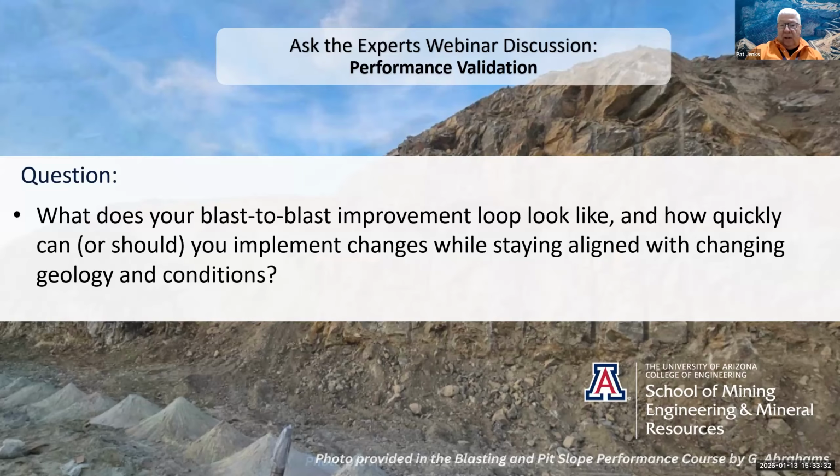Oftentimes that manifests as an increase in magnitude of displacement and velocity temporally correlated with shot time. So what's going on with our monitoring tools? And then, review the vibration data. Are we at or below the targeted vibration and frequency thresholds, or above the frequency threshold? In reviewing that seismo data, do we see any changes in the performance?